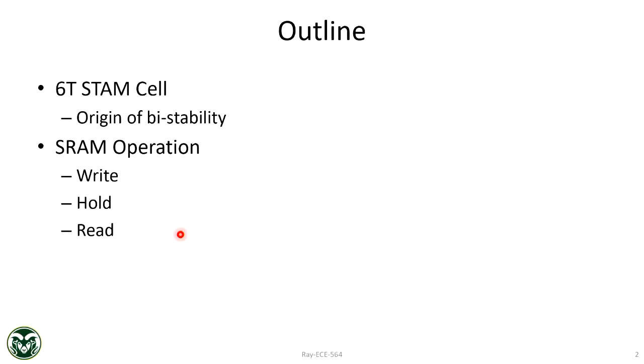One option is you can operate the memory at a much lower voltage when it is just holding data. You don't need, say, 1 volt. You can operate it at half a volt, right? So that's an important criterion: what should be the minimal voltage? Because each of those things has implications for energy consumption and reliability. So we will see all of these as we go forward. You can ask me questions at any time.